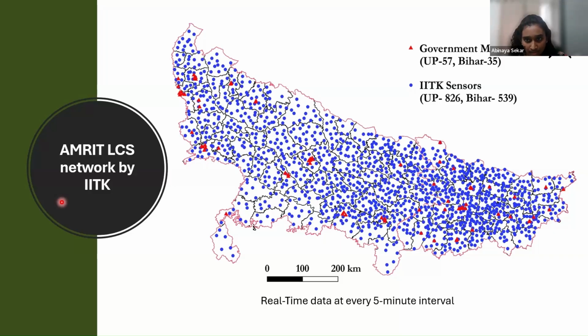Okay, and there was also another question I think you've already mentioned during the talk: what is the lower detection limit of your sensor? The lower detection range is generally 0 to 1000 micrograms. But in a very clean room, when you measure the PM concentration, it will give you some range where the PM is not actually there.